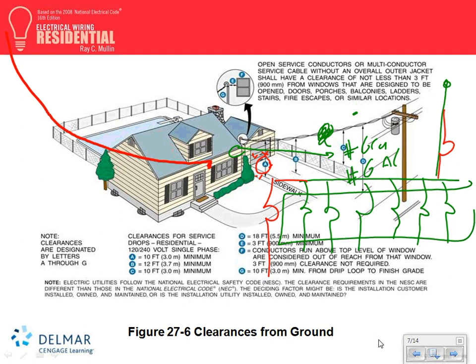I want to bring to your attention, guys, page 80 about the service, 230.79, rating of service disconnect means. Page 80, upper left, it says one circuit installation. You can have one service for 15 amps, but don't look at this one. Look at the B. 2 circuit installation, you can have 30 amps. C is the most important thing. 1 family dwelling. For 1 family dwelling, my friends, you cannot go less than what? 100 amps. How about if I have all other installation? All other installation, 60.